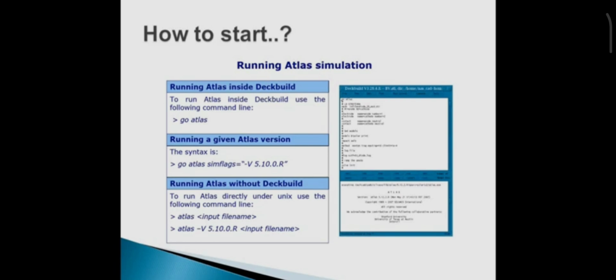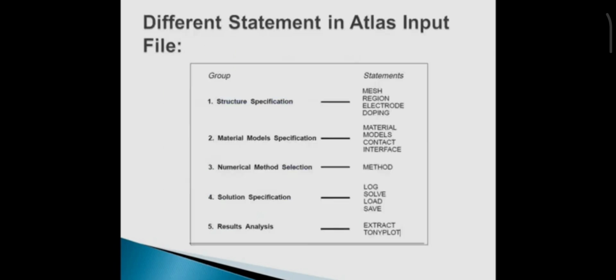Running Atlas without DeckBuild: you can run Atlas outside the DeckBuild environment, but it is not recommended by Silvaco. To run Atlas directly using Unix, use the command atlas input file name, or atlas version name and input file name. Next slide please.